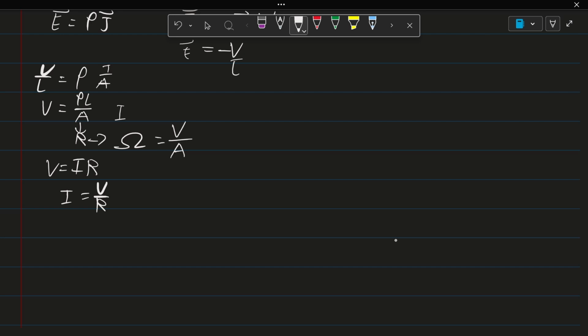So there are certain ideas that you could actually use when you're describing a circuit, thanks to this idea of Ohm's law. One of them is the open circuit. So an open circuit is where current is zero, but there's a voltage, and voltage is voltage. So this idea means that there's a resistance of pretty much infinite. Well, pretty much very big. So this is the idea of an open circuit, that there is a high resistance between one end as well as the other end.